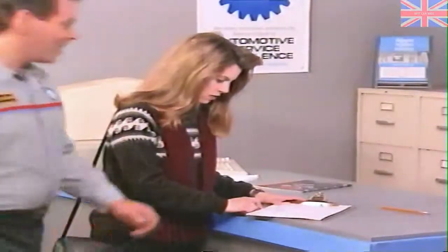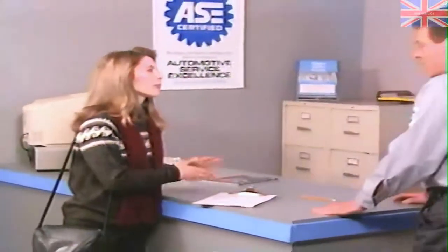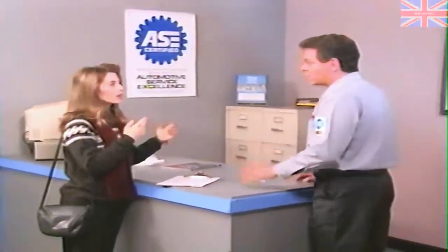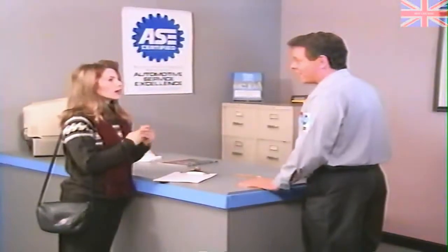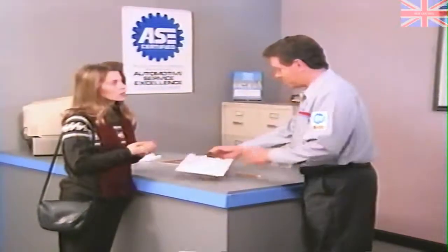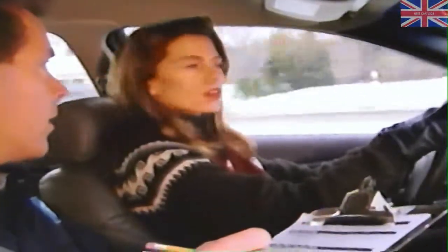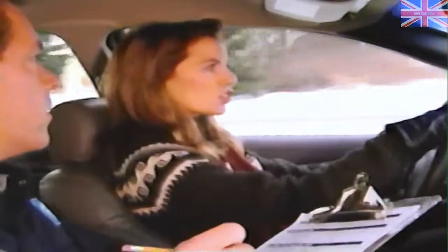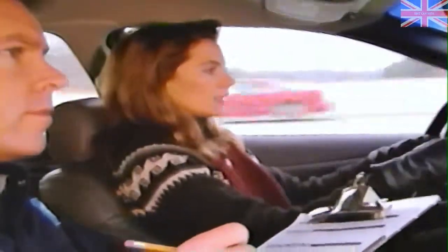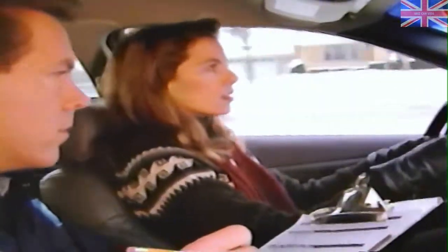The first step is to confirm and reproduce the condition as described by the customer. Because of the complexities of NVH problems, you should try to speak directly with the customer to avoid any miscommunication. It's best to have the customer with you in the vehicle when the problem occurs. Once you and the customer verify the complaint, you can then determine related symptoms.